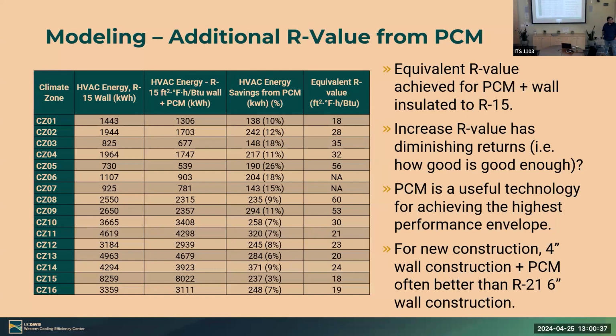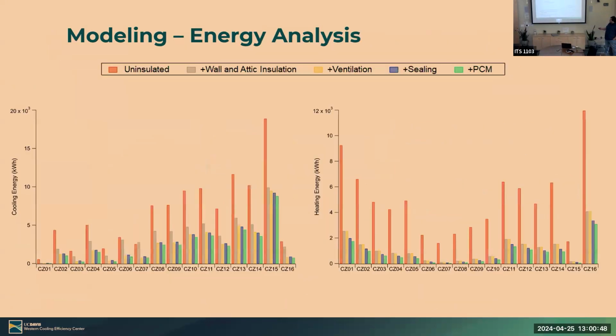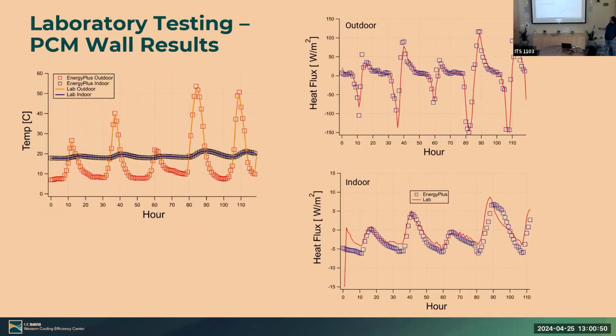And what was the nominal melt temperature of the PCM? For our case, it was around 71. On average, yeah. Just to go back a couple slides, we did ensure to account for that. So looking specifically at these temperatures, around 20 C is what we were specifically concerned with in terms of validating EnergyPlus.